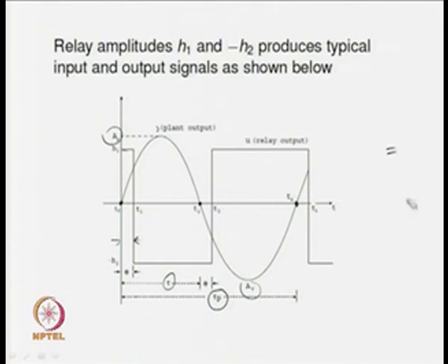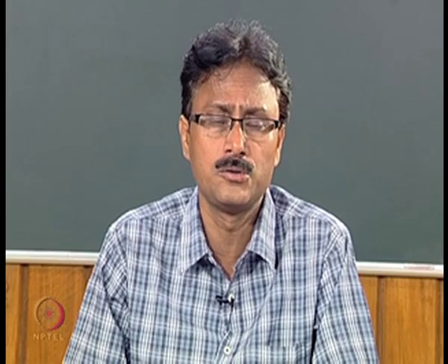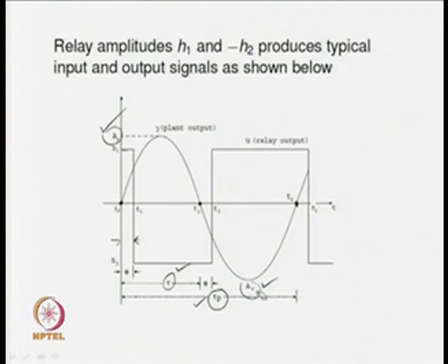So, what are the measurements one has to take from this output signal? Those are the peak amplitude AP, another peak amplitude given by AV, the half period tau and the full period tau p. So, these are 4 distinct and different parameters, measurements one can obtain from the output signal. What benefit do we get from making more measurements from the output signal? It is possible to estimate more unknowns associated with the transfer function model. So, more measurements, more equations, more unknowns can be estimated. This is the other advantage we have got from employing the asymmetrical relay during the relay test.